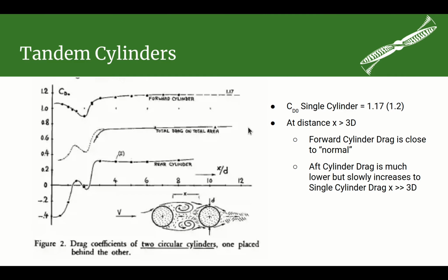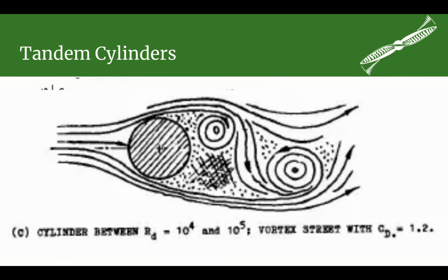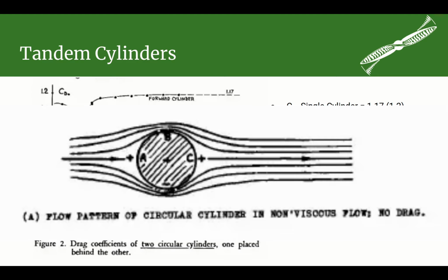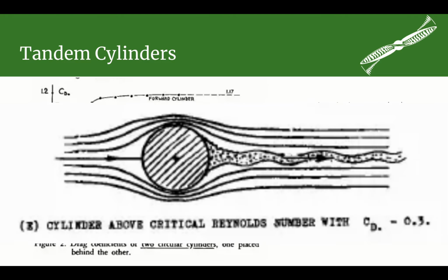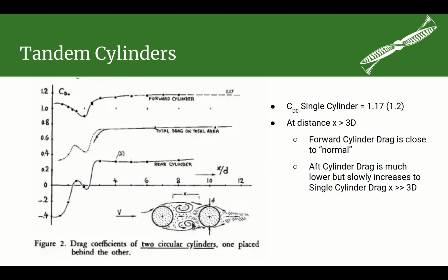So in this particular case, at around 500,000, you're typically going to get a vortex above and below a cylinder. So it's not going to be alternating one to the other. It's not going to be laminar, and it's not going to be just plainly turbulent. So at this Reynolds number, you're going to have one above and one below. At different Reynolds numbers, you're going to have different drag values than what we're going to talk about here, but this is really a pretty good representation.